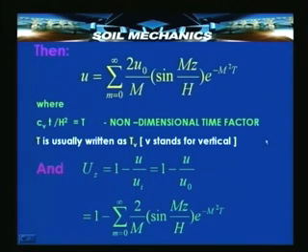And Uz, on the assumption of equal excess hydrostatic pressure over the entire depth at t equal to 0, from that, and if that value is equal to u0, we get the degree of consolidation at any depth z in terms of again the parameter capital T, the parameter h. The parameter h that has come here is known as the longest drainage path, because if you recollect, all these equations have been derived on the basis of the time taken for flow to occur, that is the rate of flow of water out of the element.